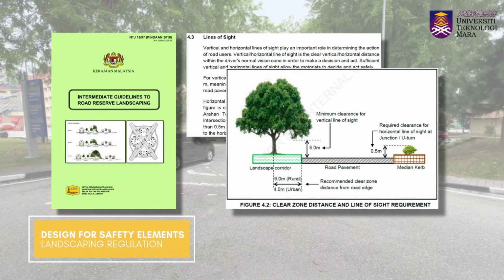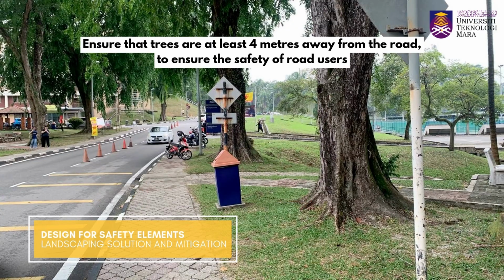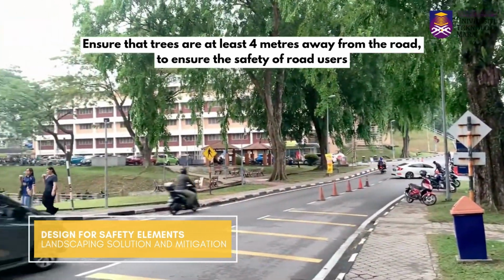According to JKR, Nota Teknik Jalan 19/97, planting setback distance under Chapter 4.3, which talks about lines of sight, Figure 4.2 suggests that for urban roads, the large trees and shrubs should be planted at least 4 meters away from the road. These setbacks are crucial to provide vertical and horizontal clearance to avoid branches or trunks posing a hazard to the road users.